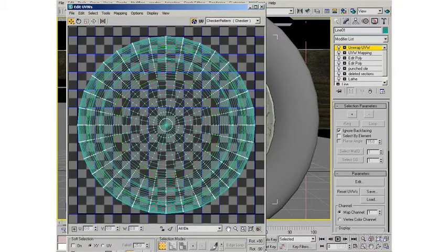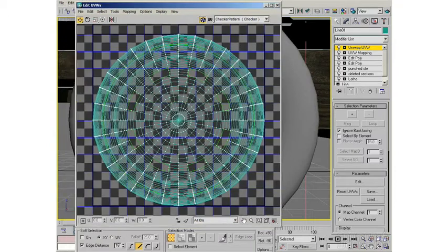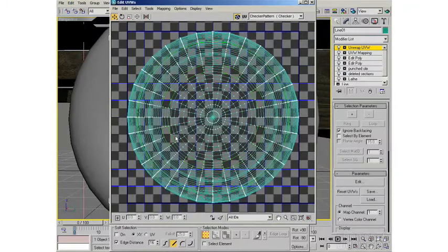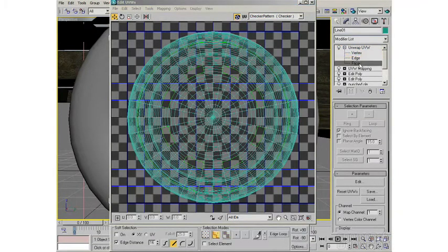And now this would look familiar to you if you've ever done UVs in another application. This is how most apps deal with UVs. You have to edit the UV map. This is the unwrapped, 2D version of what I've just done, and it allows you to edit individual edges, UVs. You can pick by vertex, edge, or face along there, and you can edit the specific UVs.